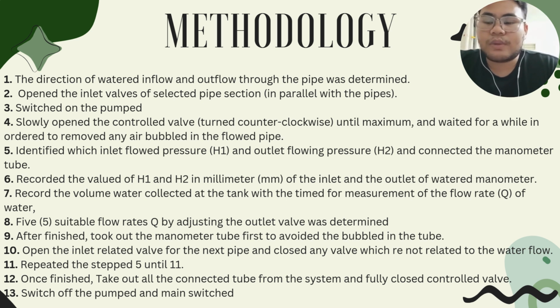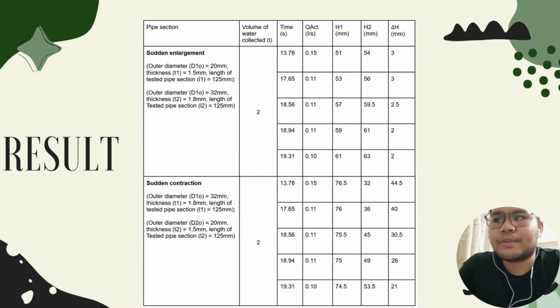For the 12th step, once finished, take out all the connected tubes from the system and fully close the control valve. And the last step, switch off the pump and main switch. This is the result for our experiment.